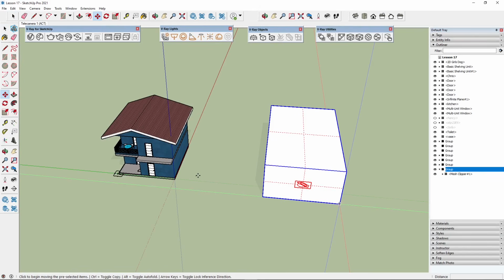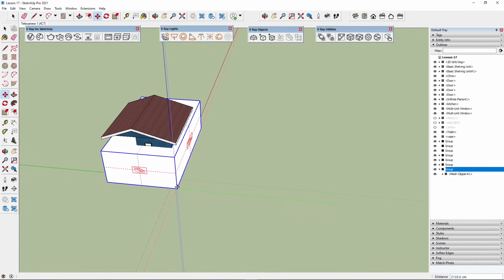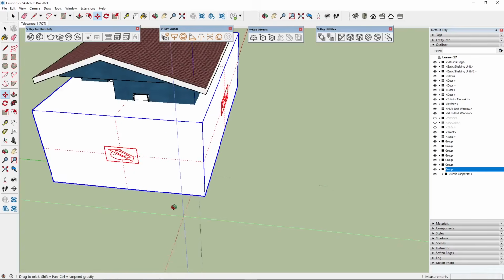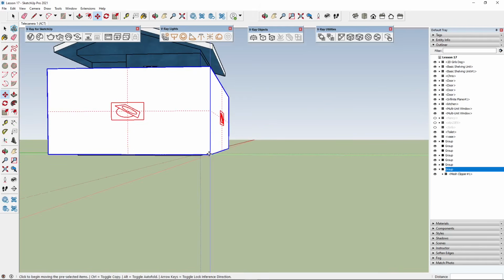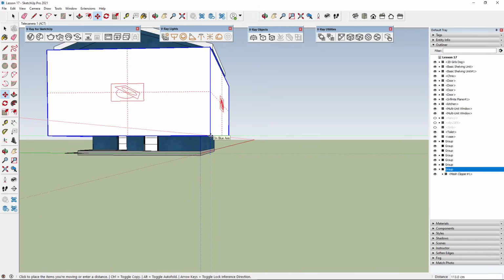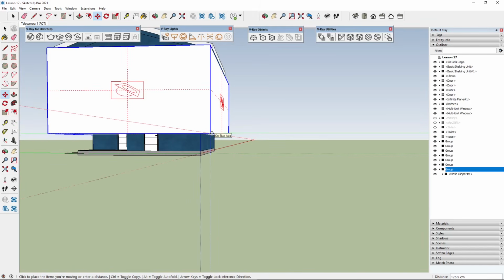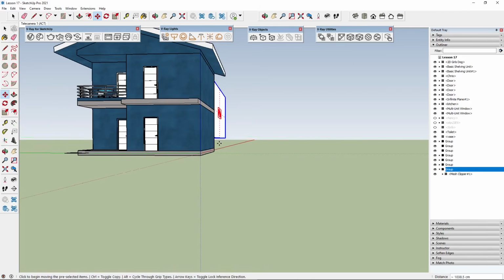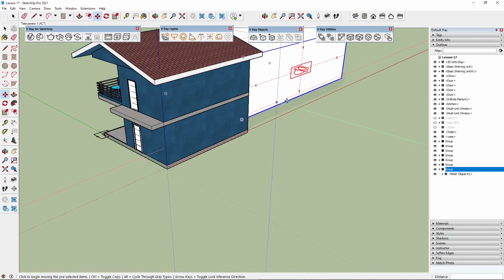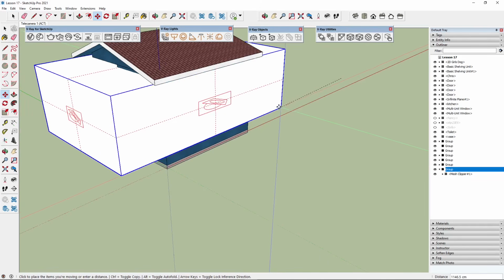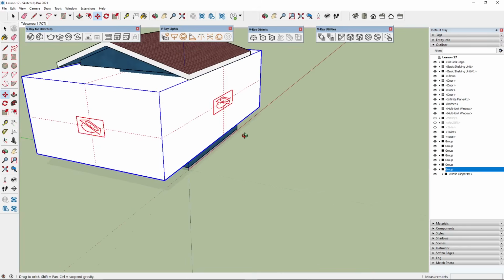So if you want to create a section, all you need to do is to place this above the project like that, and probably you need to move this up about 1 meter, 1.5 meters. Okay. Oops. Now be careful where you're gonna snap here, and there you go. You can also scale this.